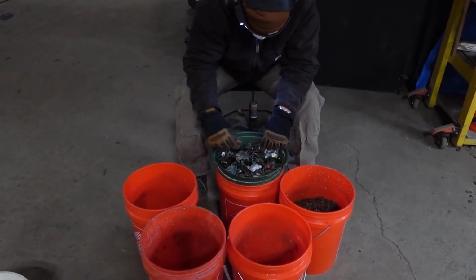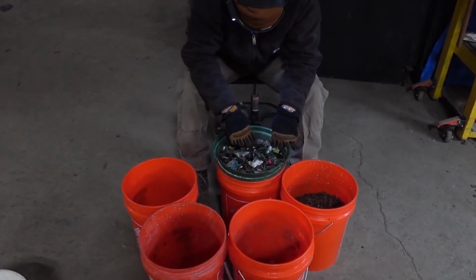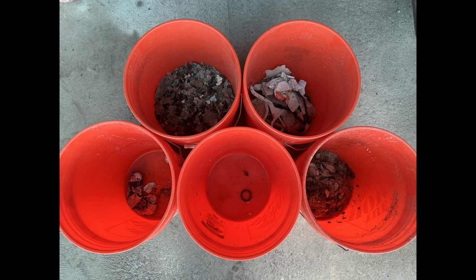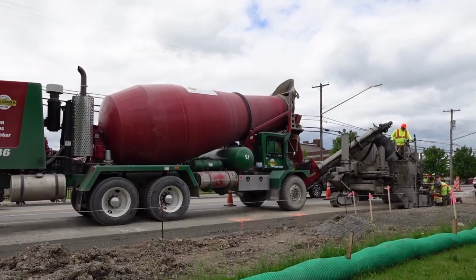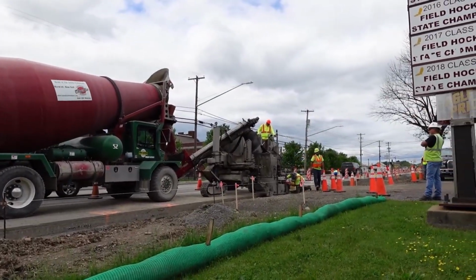Next, we complete a full manual sort of the sample. This is the most reliable way to determine MRF glass composition, and it allows us to break the sample into our 5 main categories. When utilizing MRF glass for concrete, a more robust washing process with water is needed to avoid air entrainment problems. This water soaks into our waste materials and significantly increases their weight and thus the disposal